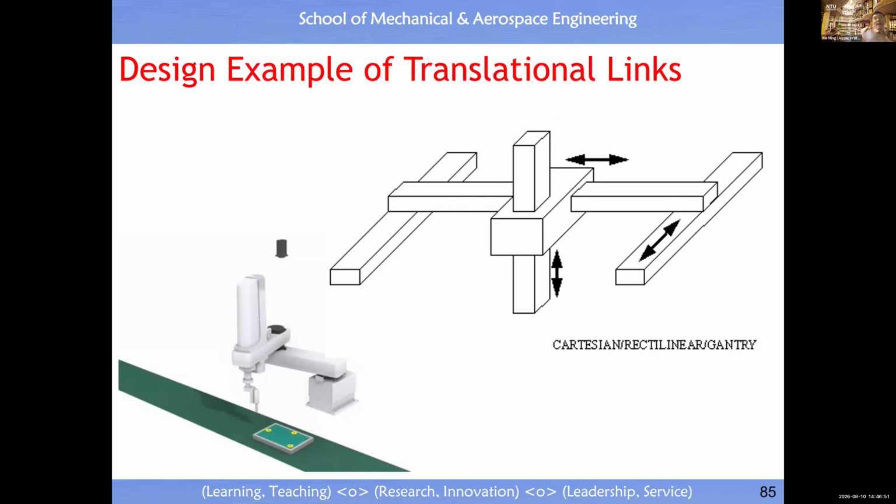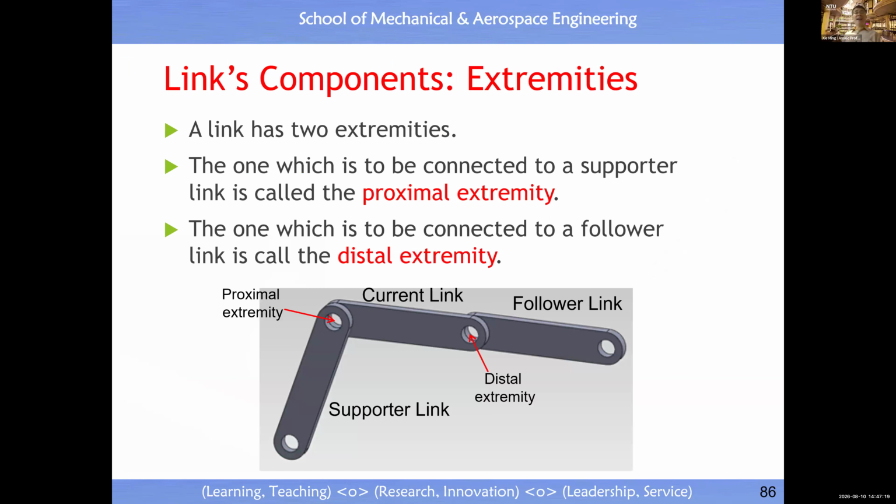So this is another example, okay? A joint will constrain the motion. This is another convention in robotics: each joint will only enable one degree of motion. This one degree of motion could be rotary motion or translational motion. So this slide shows you translational motion. You see the link can, in this case, only undergo translational motion. Okay, clear. And then what are the parameters of a link?